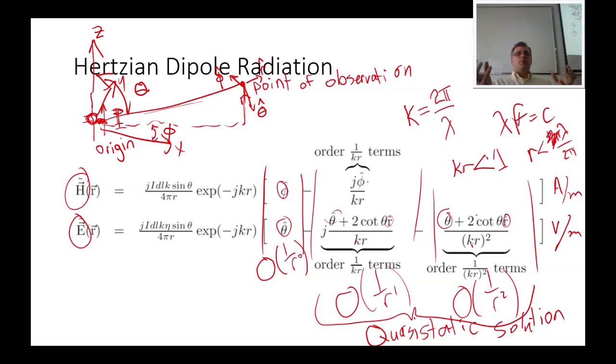What does that mean? Well, remember what a Hertzian dipole does. It's moving charge up and down, up and down at some sort of frequency. That means positive charges are depleting in one region of space and accumulating at another, and then that's reversing. So first of all, you're going to have some inductance due to that, because you've got a current moving and there are going to be magnetic fields swirling back and forth around that.